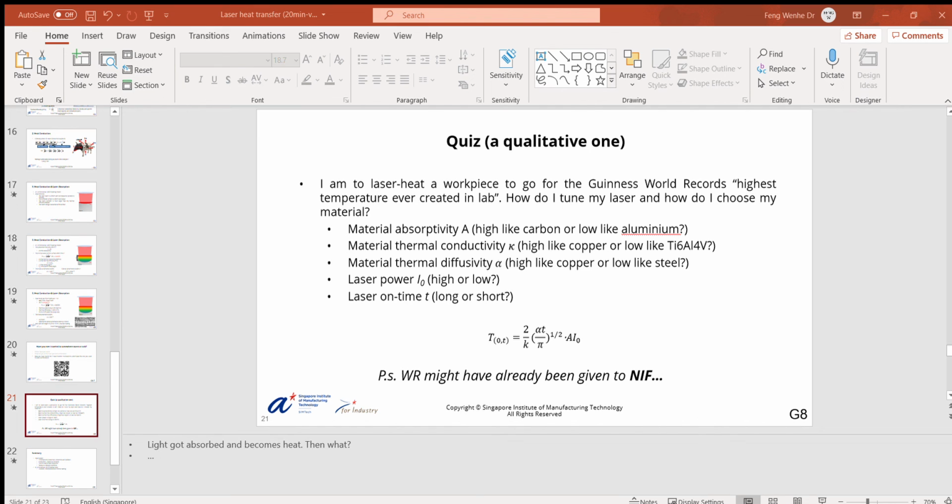All right, so I think we have covered the following contents today. We have discussed the heat transfer's definition and 3 mechanisms. And we have introduced the microscopic mechanism of conduction, which is the molecular collisions. We've gone through Fourier's law of heat conduction. We have compared steady and unsteady conditions, and then introduced very quickly a one-dimensional laser heating model. And we realized that is something localized, instantaneous, and intense heating, which is quite a powerful tool for our material processing applications.